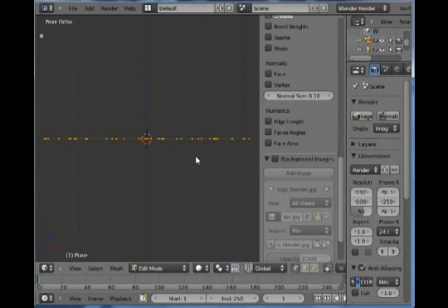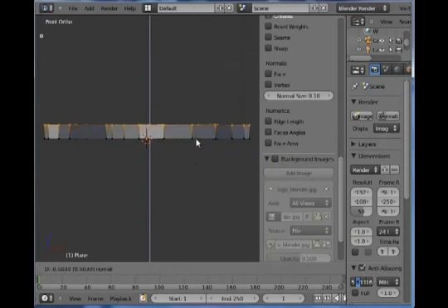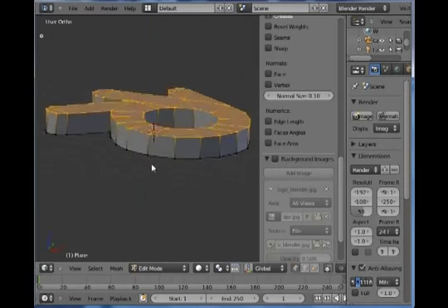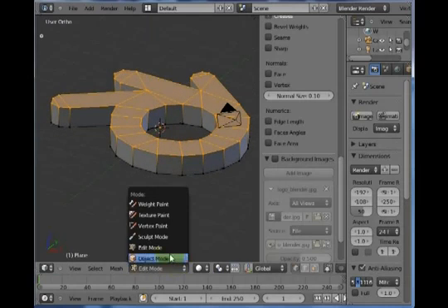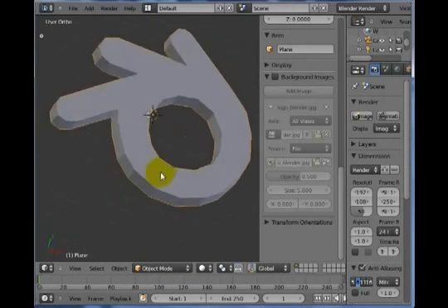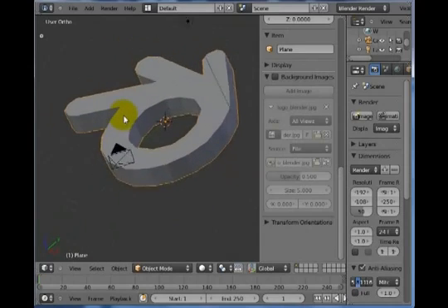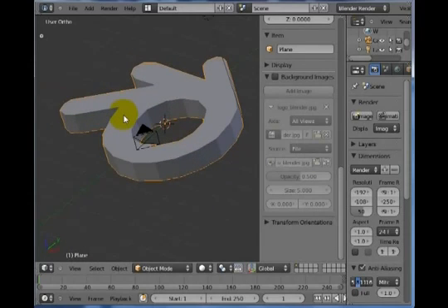And now when you look at it, let's go back over to object mode. Now it's starting to look like something. Okay, so again, this exercise is background images, creating faces, and extruding things will work pretty well. Now, what I want to do is go back and let's finish our lighthouse activity.